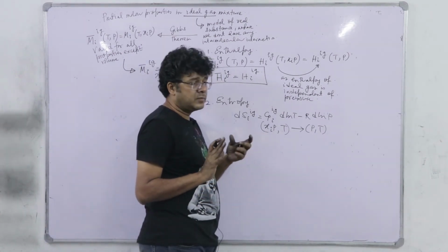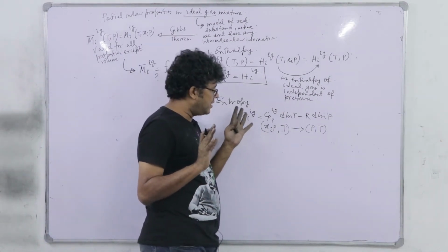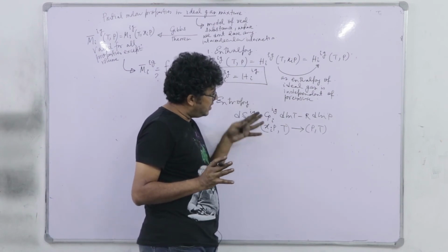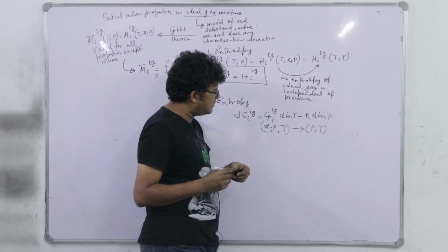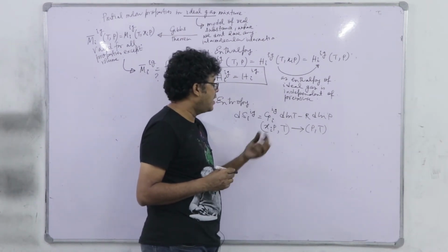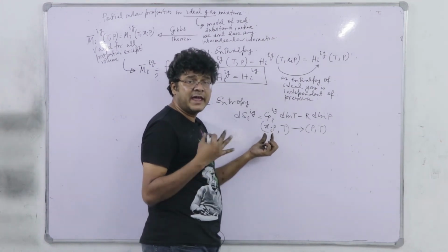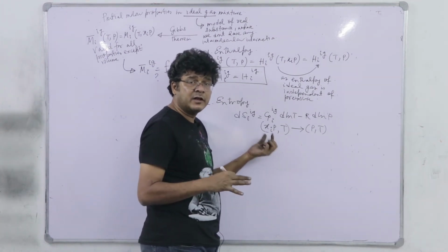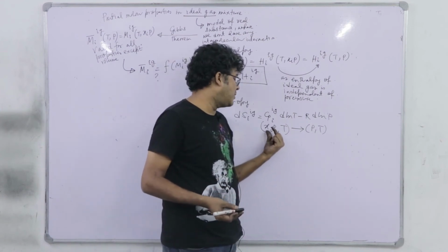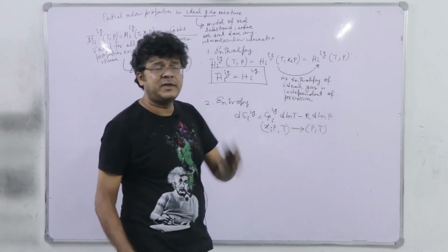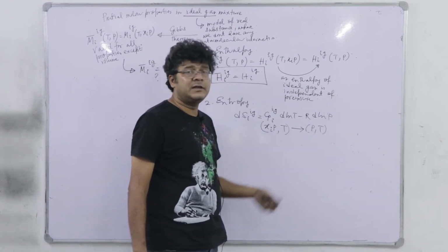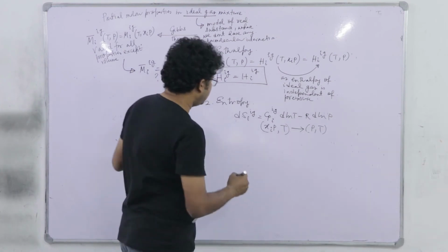But think like that we are integrating a pure species ideal gas entropy equation from a pressure it would exert if it is in a mixture with a mole fraction Xi. So, definitely though I am writing it as xi P, xi P has got some numerical value. So, from one numerical value to another numerical value we can obviously integrate.